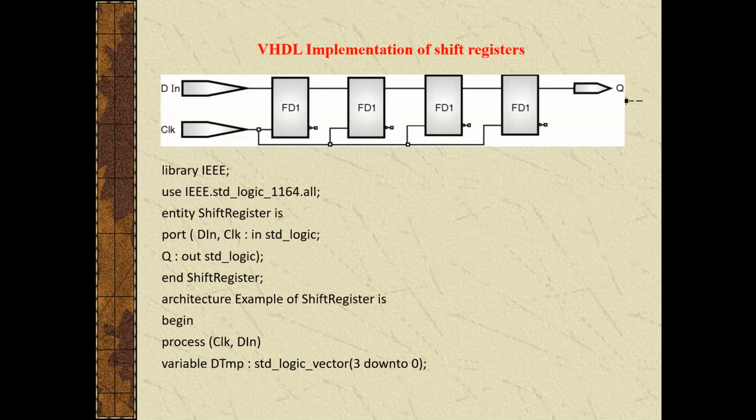For the serial to parallel data conversion, the bits are shifted into the register at each clock cycle. When all the bits are shifted in, usually 8 bits, the 8-bit register can be read to produce the 8-bit parallel data output.